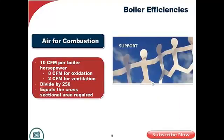Now, the other thing that's very important to keep in mind when we're talking about combustion is supplying the proper amount of air for that combustion process. And a good rule of thumb that we've used over the years is 10 CFM per boiler horsepower. 8 CFM of that, of course, is to support the combustion process, to oxidize the fuel, and 2 CFM is used for ventilation.